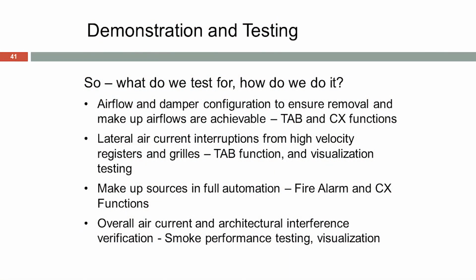So what do we do? What do we test? How do we do it? We want to know that the airflow and damper configuration to ensure removal of the makeup airflows are achievable. We can do that ahead of time, right? We don't need smoke for that.